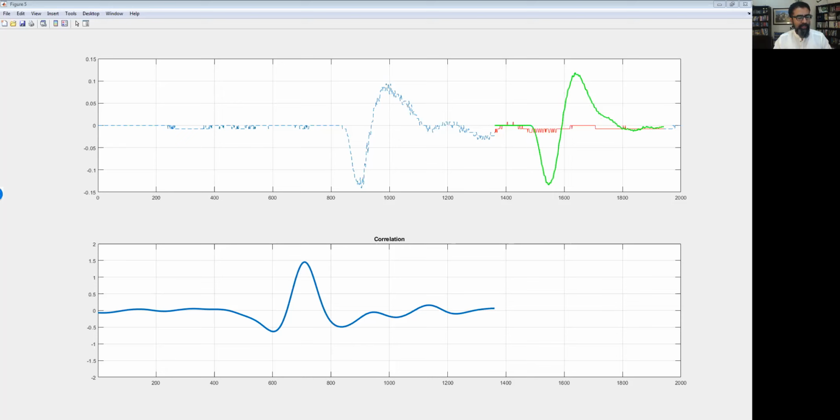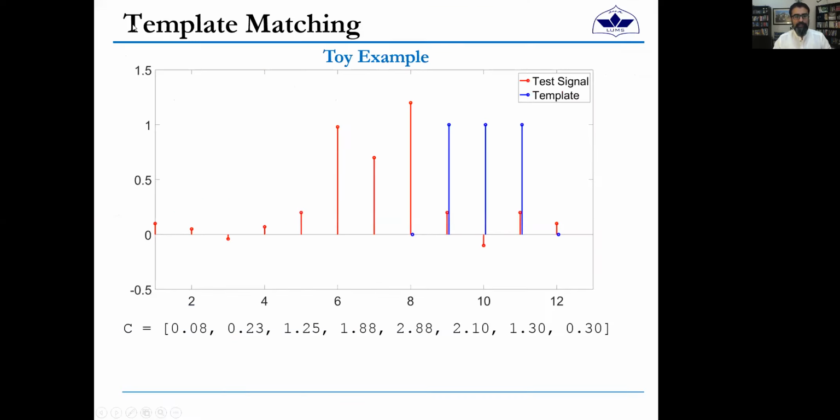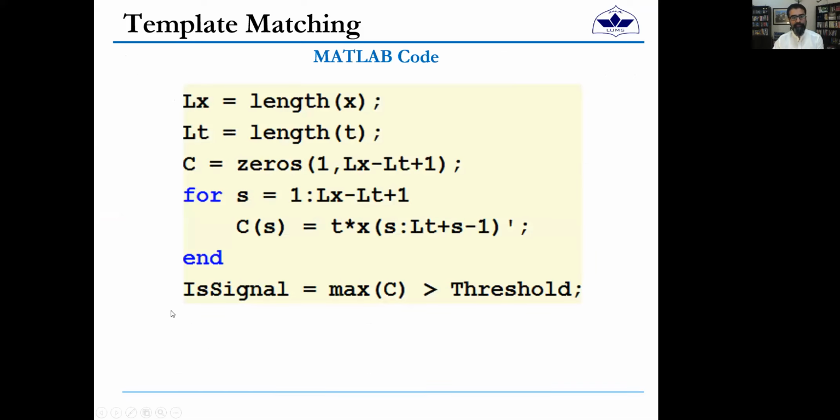And so this is going to be one of the lab tasks, right? Right, so all right. So you compute the maximum correlation with the threshold, and if it's above a certain threshold, you say it's a gunshot, otherwise it's not. Okay?